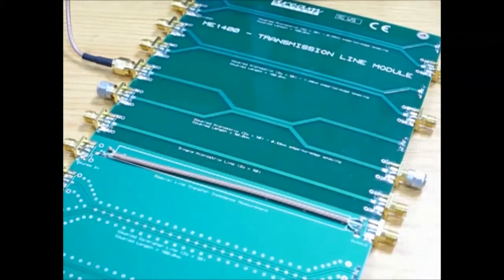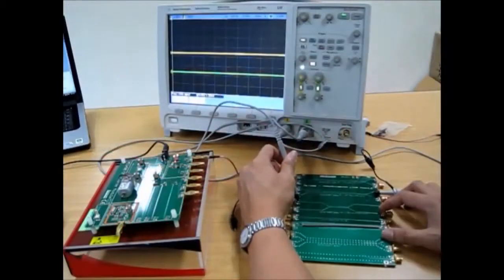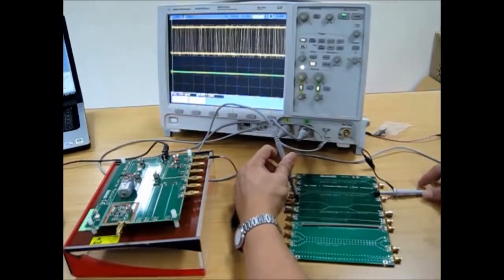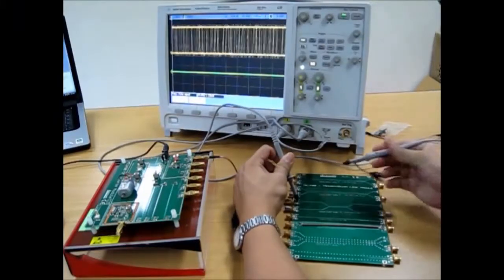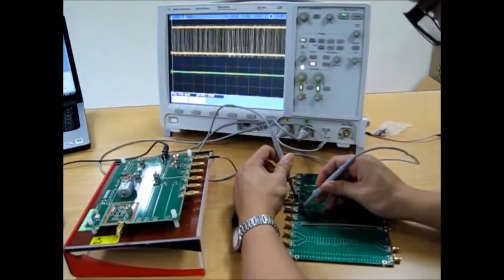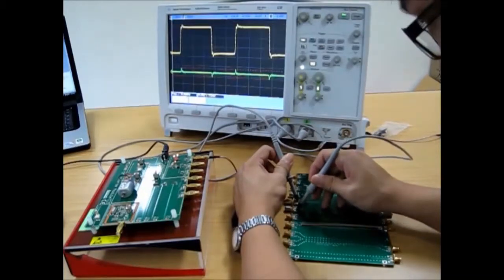Now we would like to examine how the length of a copper line affects the crosstalk level. This copper line has a 0.56 mm edge-to-edge spacing, which is the same as the first copper line, but with a shorter copper length of 50 mm, half of the length compared to the first setup. Use probe 1 to capture the high-speed pulse on the active trace and probe 2 on the induced near-end crosstalk point.